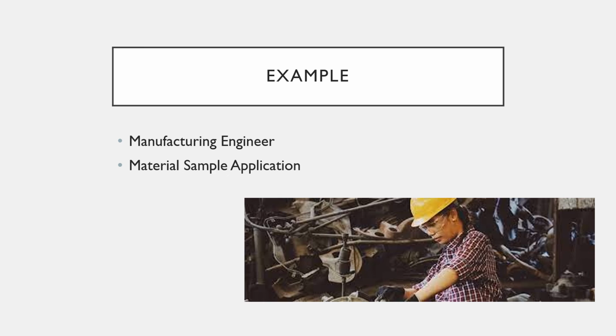And I take the 50 bolts, I measure them, so I get my sample mean and my sample standard deviation from my measurements. Then I can find my z-test statistic with the formulas on the previous slide, and then see if they fall within my confidence range, the z values. And if they don't, I reject my null hypothesis, that no, the values coming off of the machine are not within the range that I want them to be. So I'm going to need to look at doing repairs or creating a new piece of equipment there in this example.